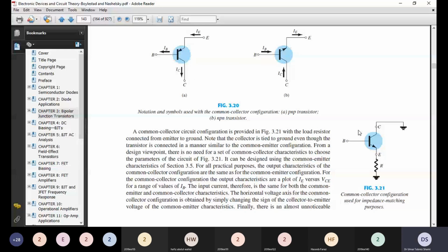Now, in electronics, impedance matching is the practice of designing the input impedance of an electrical load or the output impedance of its corresponding signal source to maximize the power transfer or minimize signal reflection from the load. A source of electric power such as an amplifier or, for example, a radio transmitter has a source impedance. What is source impedance? The source impedance is the impedance present in the source, which is equivalent to an electrical resistance.